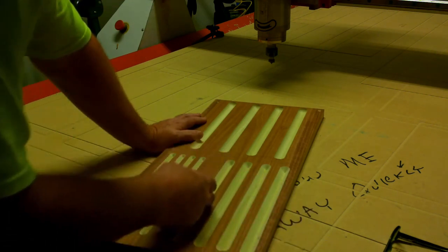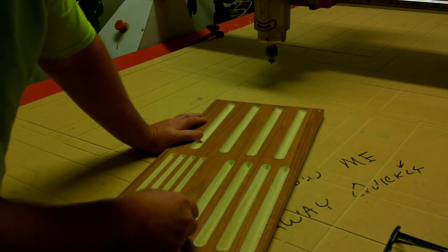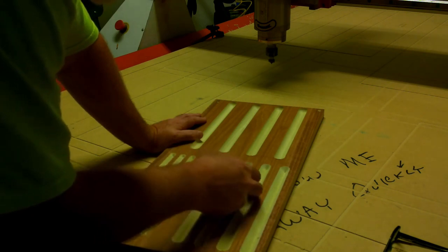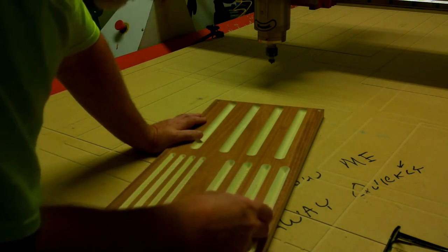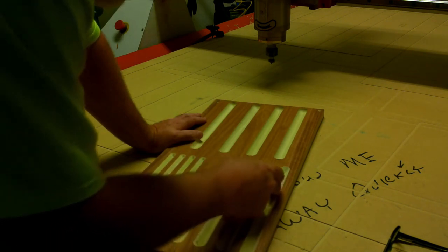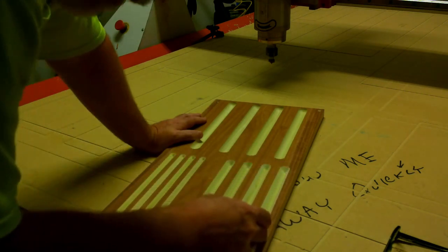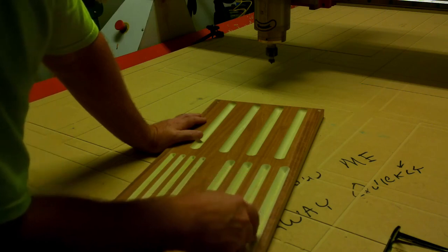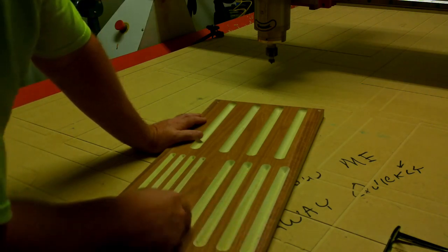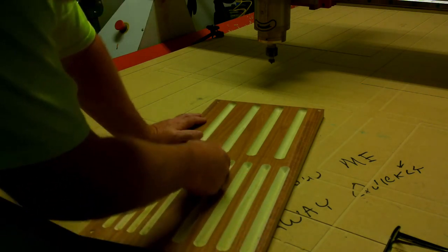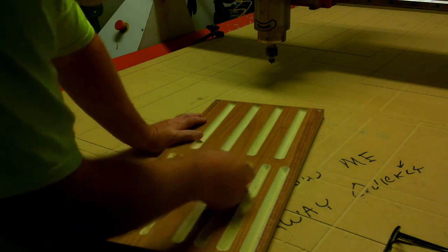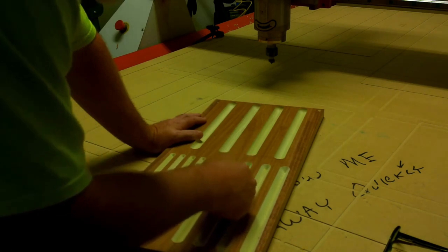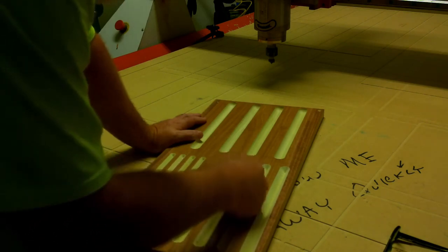The second in quality is the V-bit. And the problem with the V-bit is every single one of these has got a little bit of roughness down in the bottom. Let's just call it bad. Okay? But the best one is the fastest, 18,000 RPM. The slow one actually did pretty well too, but for some reason the 14 and the 16,000 RPM, the 16,000 is just really coarse and rough.